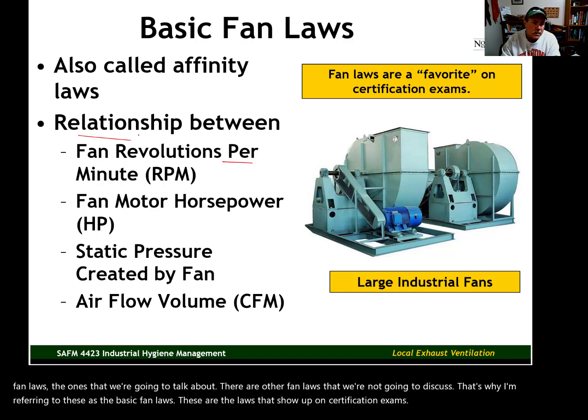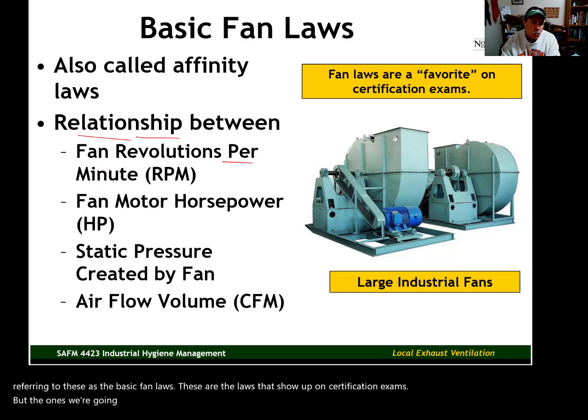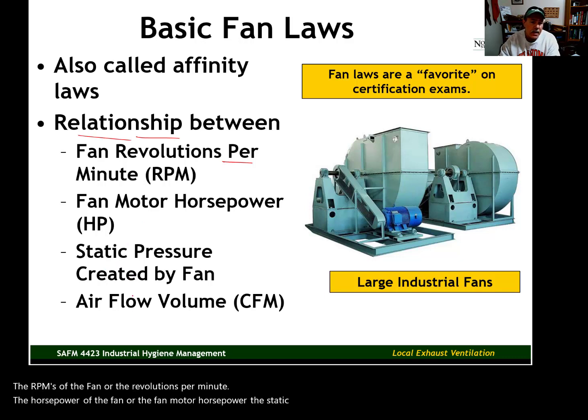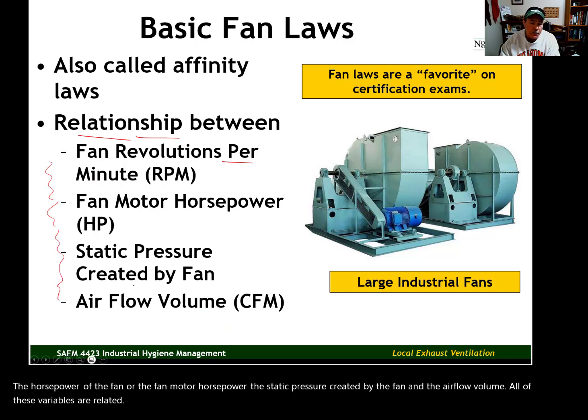But the ones we're going to discuss look at the relationship between the RPMs of the fan, or the revolutions per minute, the horsepower of the fan, or the fan motor horsepower, the static pressure created by the fan, and the airflow volume. All of these variables are related. And these affinity laws or fan laws show us how they're related to one another.